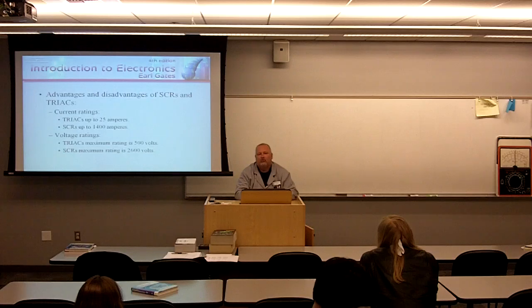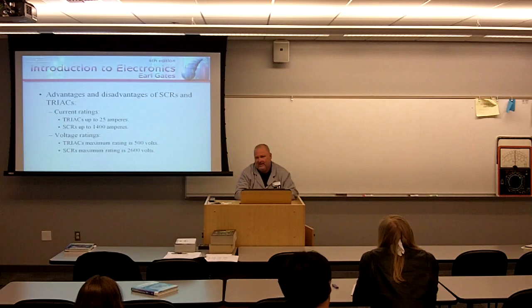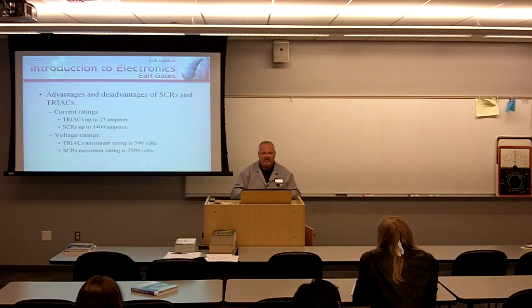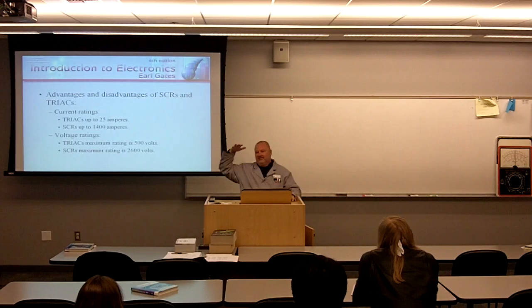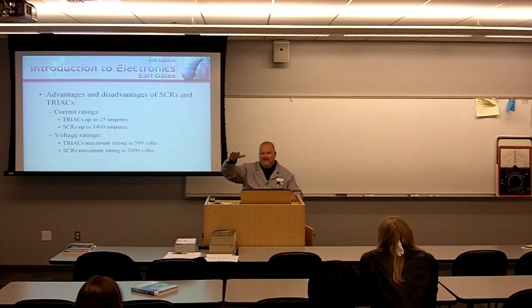Has what's known as pilot control lighting. So what I can do is when I'm flying, and normally the lights shut themselves down after a certain amount of time. So what I'll do is I'll fly over there, and then on instruments, I'll start the approach to the runway. So I'm coming down, coming down, coming down, and it's just black in front of you. You don't see anything. And then there's a frequency that I could dial in, and then typically click.